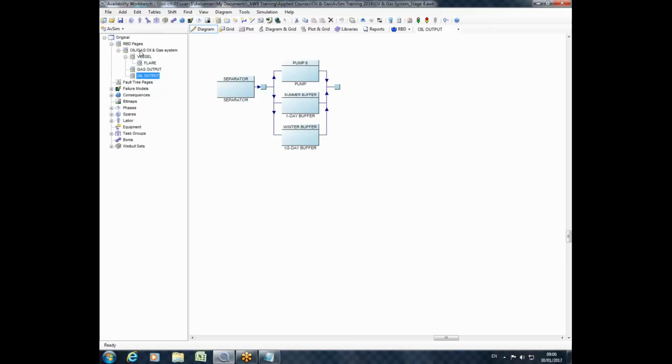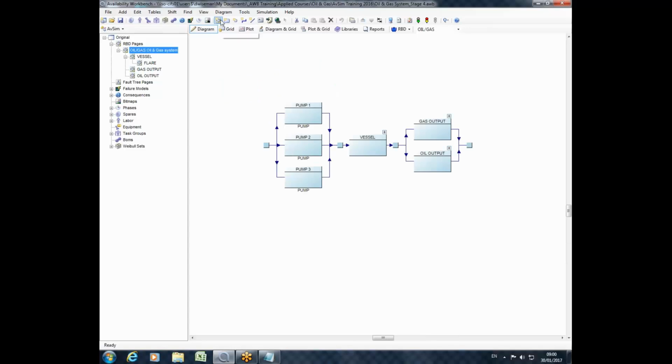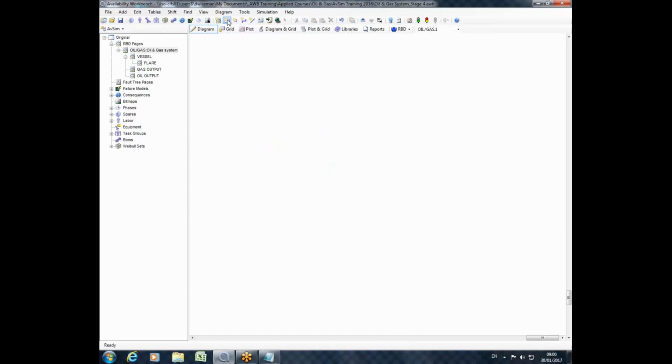Now the program allows you to build multiple systems in the same project if you wish, and you can see here the toolbar buttons for putting this together. You can add blocks, nodes, and connections to connect all this together, and you can select a block, click page down, and then start adding more structure inside that block and create what we call subsystems.